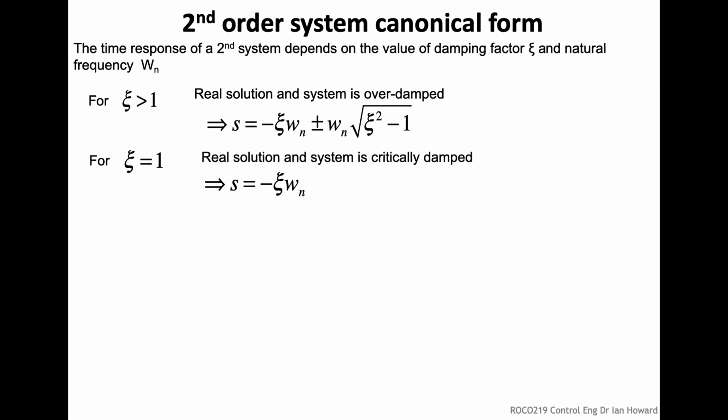In fact, this damping has made sure that the system is still non-oscillatory, right? We've got no complex parts in this solution at all, but zeta is as big as it can be without actually being overdamped. That's the important thing, and this is actually known as critical damping.